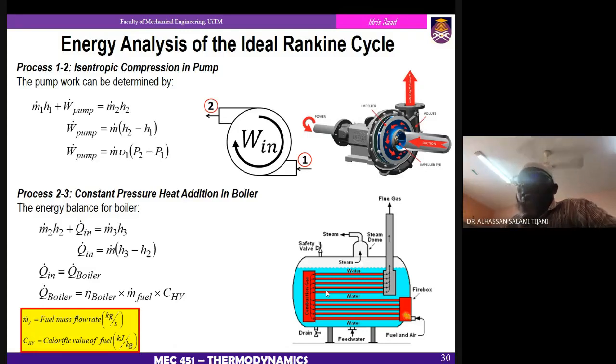Okay, throughout the cycle, compression and expansion processes occur, and the combustion process is replaced by a heat addition process. Then we look at the various cycles involved in the transformation of this actual cycle into an ideal cycle. So the ideal cycle of the gas power cycle is called the Brayton cycle, and all the processes associated with the Brayton cycle are reversible.